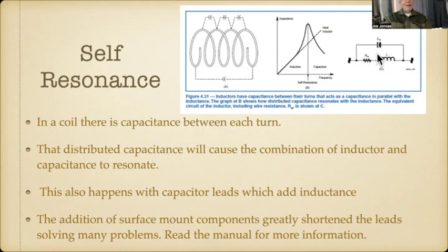I've got a little inductor tester. If I take a wire, look at my little picture down here. If there's a wire this long, it's an inductor. And if you're working at 2.4 gigahertz, which is a lot of our phone system in our houses and stuff like that, that's a big inductor at that kind of frequency. At 3.5 megahertz, you don't have to worry about it.